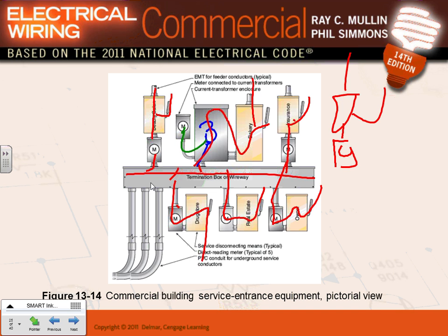You're going to say no, we can't get you in here. They're paying money for you. Thank you. You just have a main disconnect here. So you grab a main disconnect and you put it right in here. That's all. Then you can have as many disconnects as you want. Very, very important. You can't tell the tenants you can't come here because the NEC code book said that you cannot. We are in the business of solving problems, guys. You have a problem like this, add another disconnect, a main disconnect for the whole building. Any comments, any questions? That's the 6 disconnect rule.